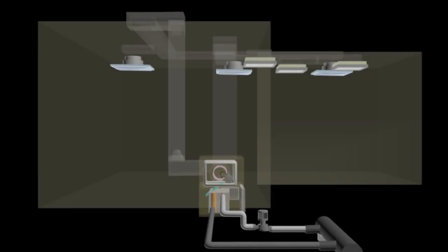For the airflow system, it is operated using an auxiliary fan which creates the air cycle from the room and mixes it with fresh air from the outside to the air handling unit and returns back to the room. The type of fan used is a centrifugal fan, powered by a motor and connected through a belting.